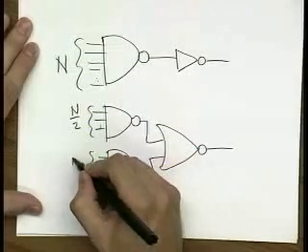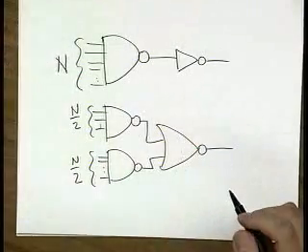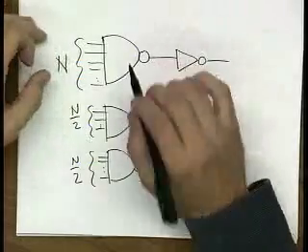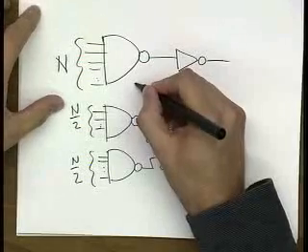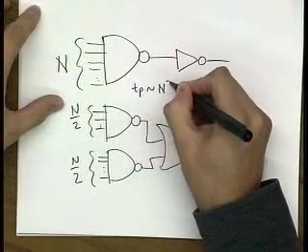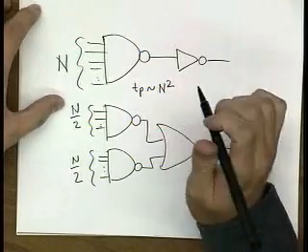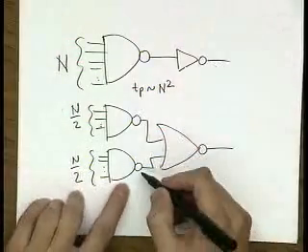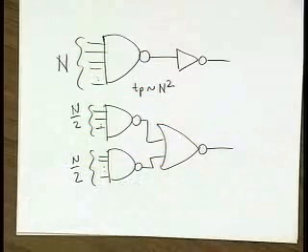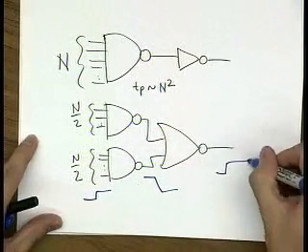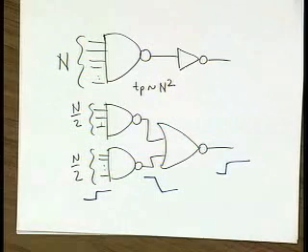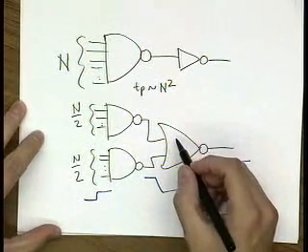Now I know that in the worst case, the pull-down of this gate is really bad, and that's the reason I'm doing all of this. The pull-down is proportional to n squared, and that's really hurting me. CMOS logic is complementary, which means if I have a pull-up here, I have a pull-down here, and then a pull-up here. When I'm cascading the gates, the bad pull-down of this gate is cascaded with the bad pull-up of this one.